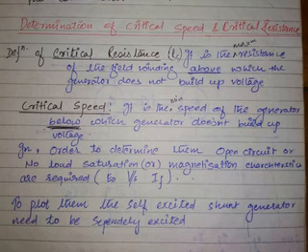Can we say that? You are plotting E0 versus phi. As you are increasing the current, flux is increasing. You are producing magnetization in the machine. This is nothing but magnetization. So that's why it is known as magnetization curve. And in this curve, you will observe the saturation point. That's why it is also called no load saturation. Why is it called OCC, open circuit characteristics? Because the generator is left open, no load. That's why it is known as open circuit characteristic.